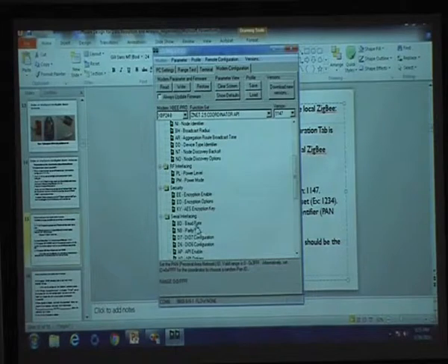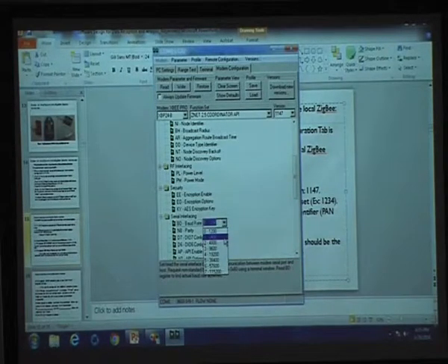baud rate here, the serial interfacing. There are different options available: 2400, 4800, 9600, 19200. By default it is 9600, so you are going to select that data rate. And one more important piece of information to be selected is